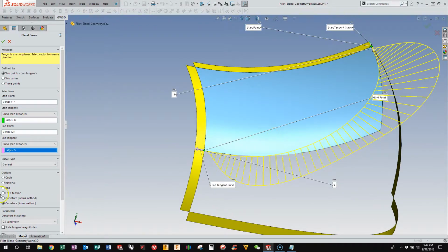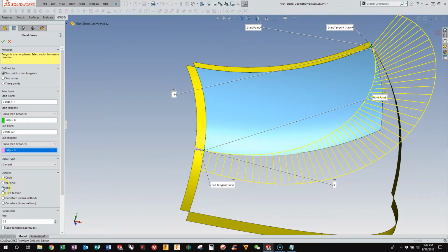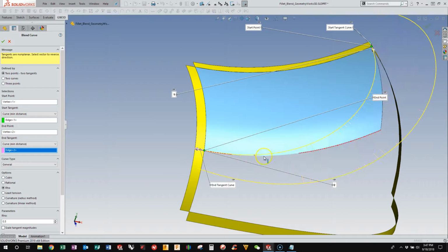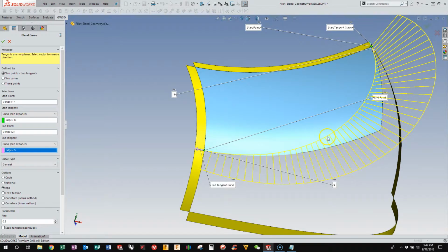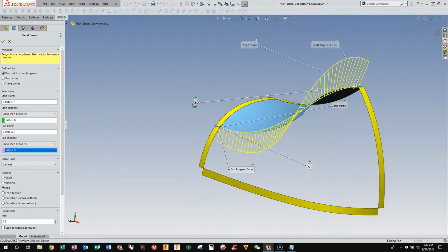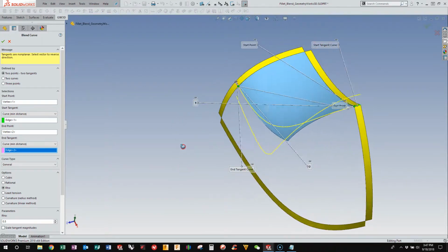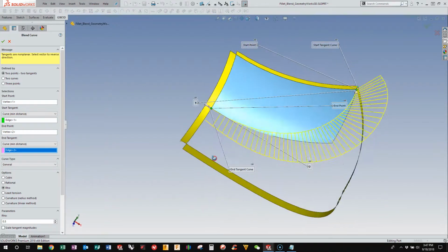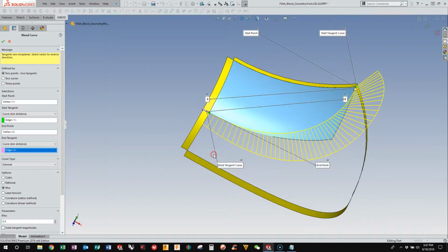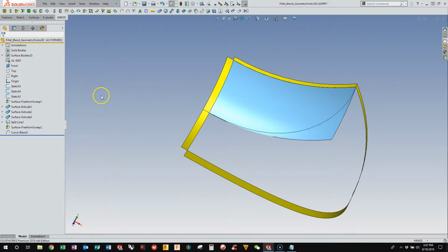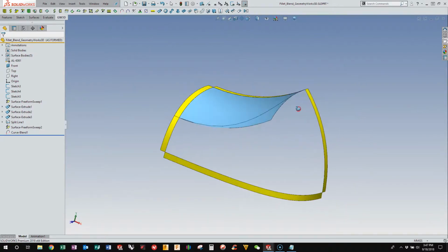And I've already built this, so I know that in this case the row solution gives me the result that I want. I want a curve that follows this surface pretty closely and is really, really smooth, because this curve is going to drive my trim surfaces. So the smoother this is, the smoother my edges will be that I'm going to trim back. So this looks really good, except that guy. So now I have this nice curve.